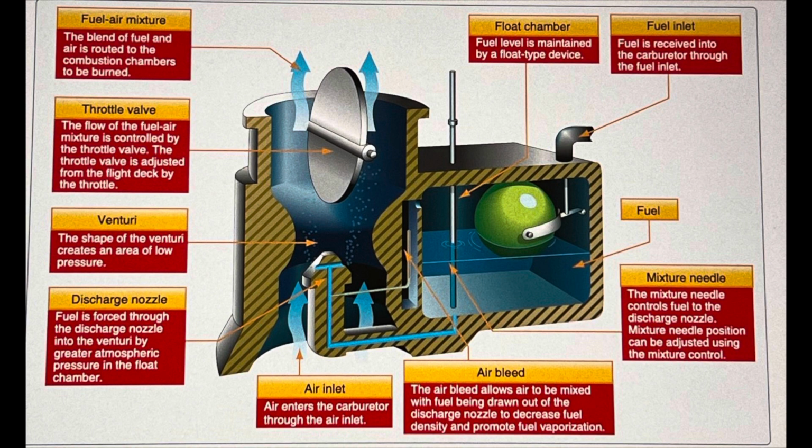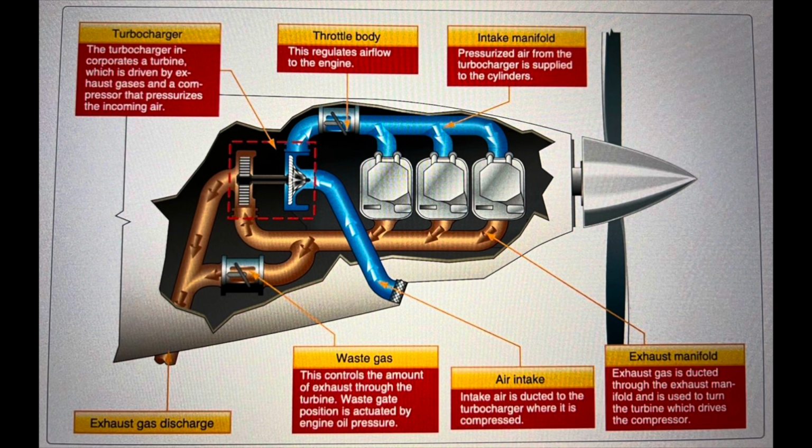So to increase an engine's horsepower, manufacturers have developed forced induction systems called superchargers and turbochargers. So these are basically what boost the horsepower of an aircraft. The supercharger and turbosupercharger systems both compress the intake air to increase its density. The key difference lies in the power supply.